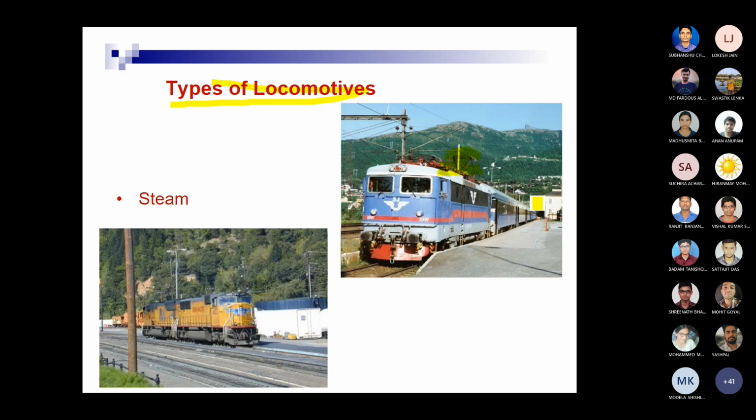Okay, pantographs are there. Normally on one engine you can see one pantograph is already raised up and operated. Another one is there, that is not in use. This is the backup pantograph. One engine has two terminals, two sides, so it may work on the front side as well as the back side. One coach contains two engines like that, so you can move them in either direction.